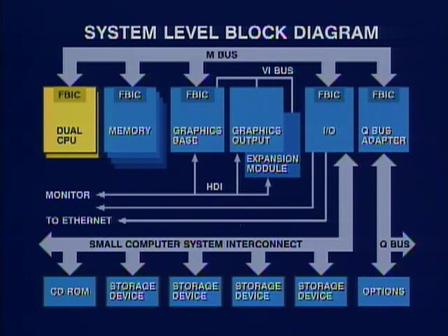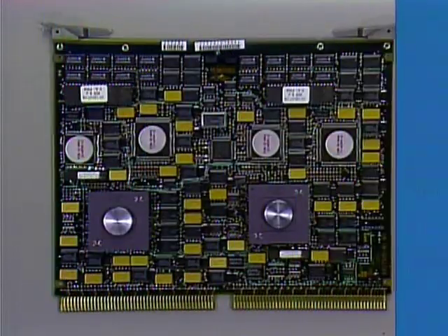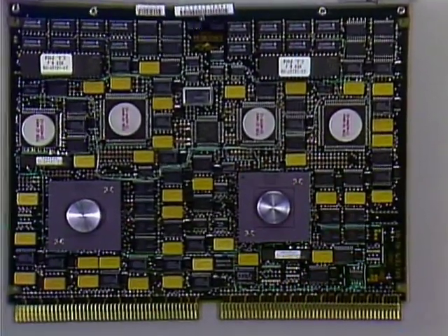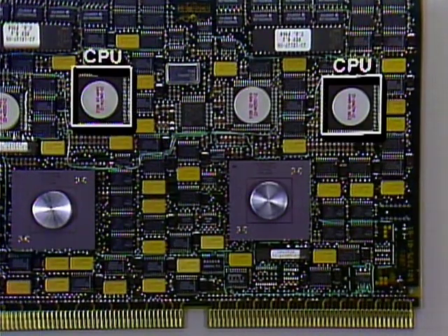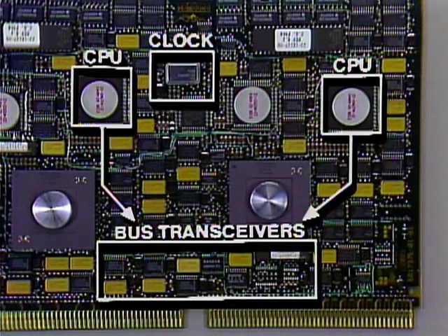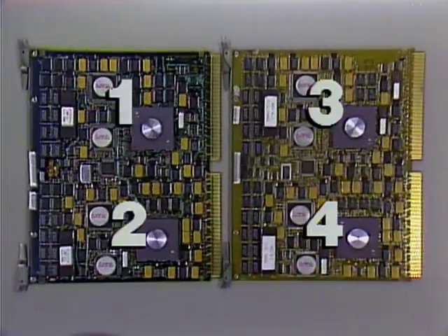At least one KA60 module is required in all VAXstation 3520-3540 configurations. The VAXstation 3520-3540 KA60 dual processor module consists of two functionally independent CPUs that share a single set of bus transceivers, clocks, and test mode connections. A second dual processor module may be installed, which provides 4 CVAX processors. The maximum number of processors supported by the VAXstation 3520-3540 workstation is 4.